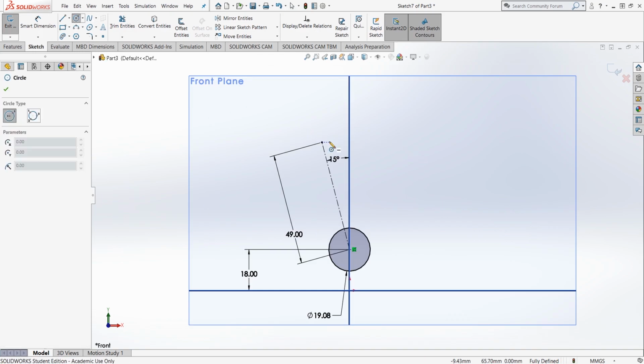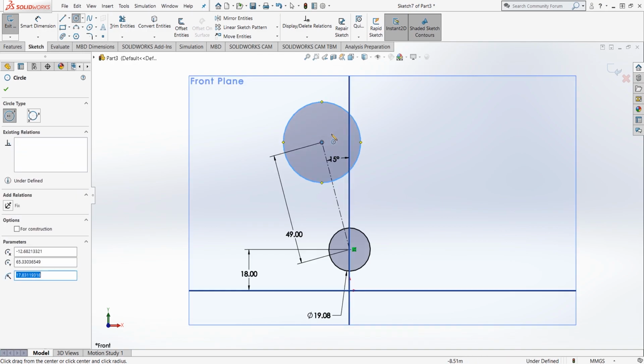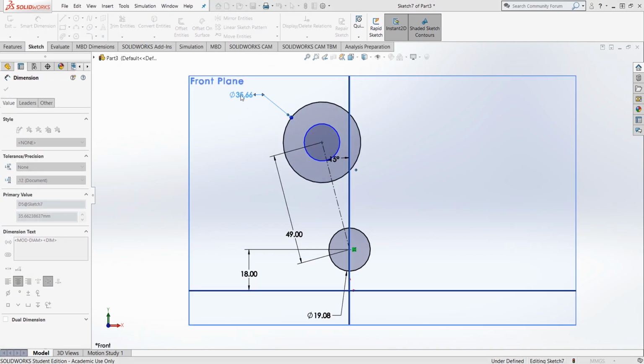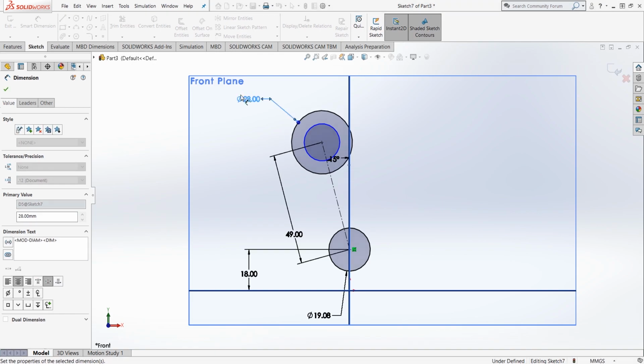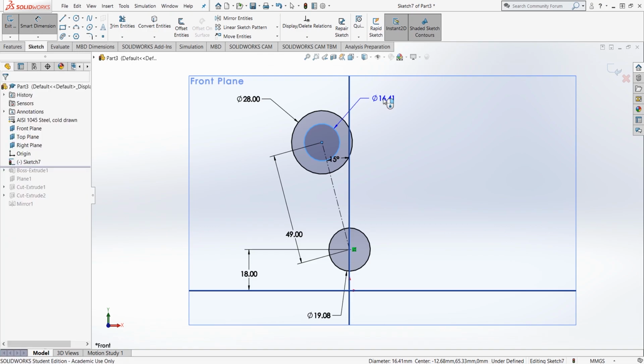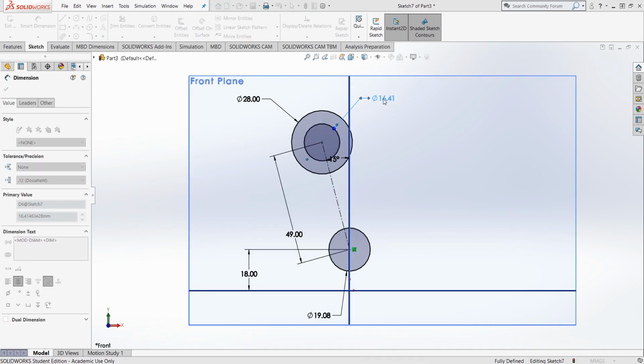So next thing I'm going to do, I'm going to add two circles up top here to get our outside radius and our inner cut. Alright, to make this nice and easy, I'm given a 14 millimeter radius, so we're just going to do 14 times 2 to make this easy. No math required. Then our inside circle is 12.75 millimeters.